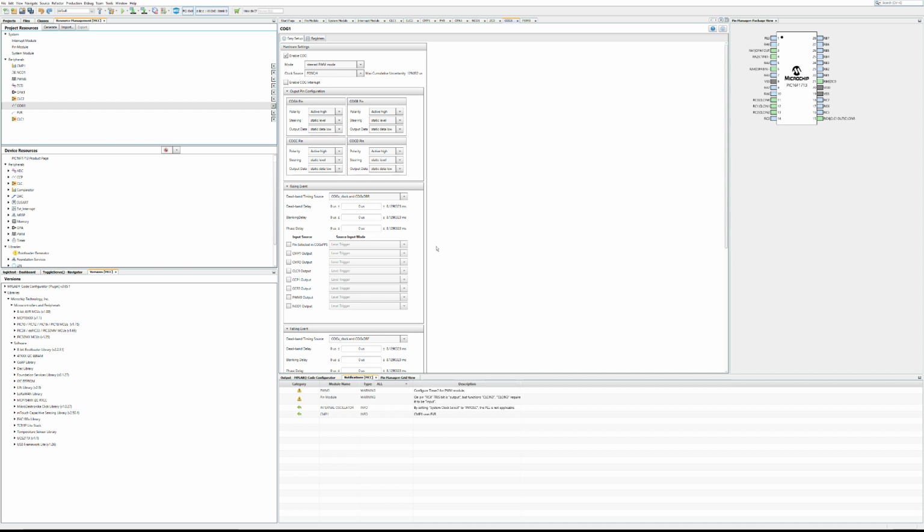Very useful in motor control or even in an inverter design, to reduce shoot through, where if the high side gate's on and the low side gate's off and you want to swap their states, if you do that at the same time, due to line capacitance and whatnot, there will be a short period where both gates are actually on, and that will give you shoot through, where your supply voltage will shoot directly through your high side and low side output switches.